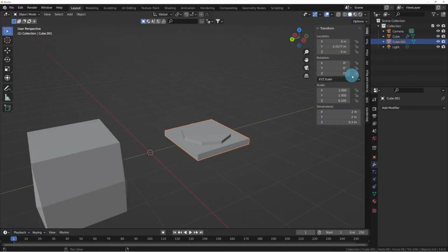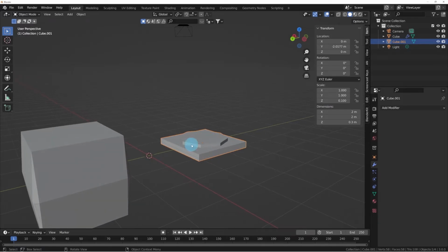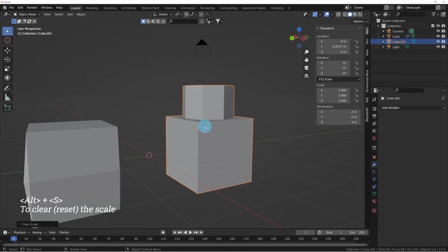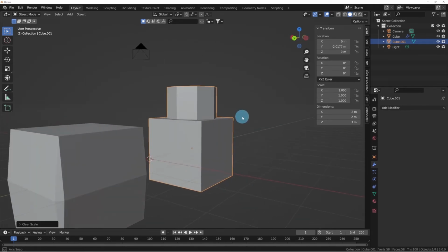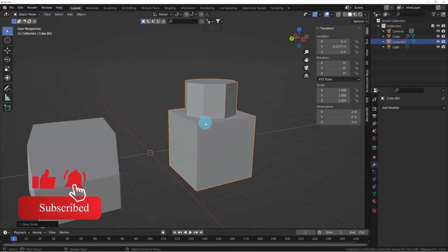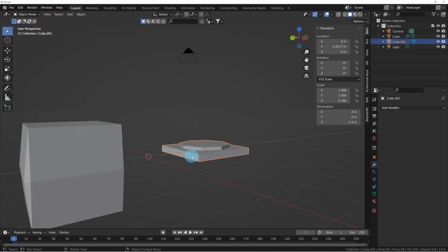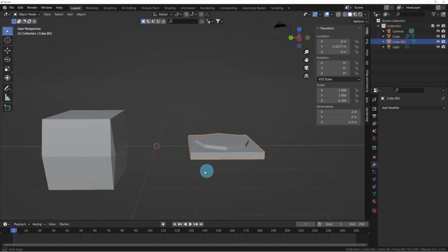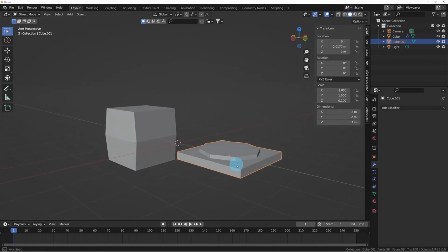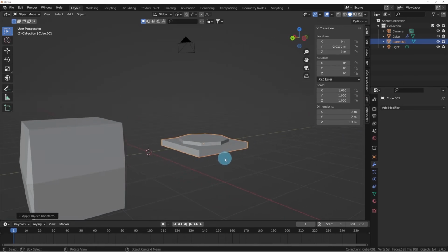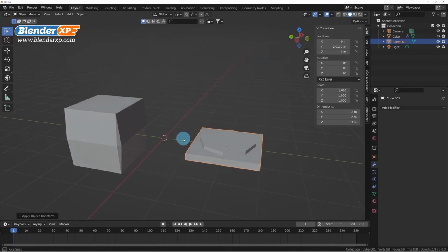This is why it happened: for Blender, this model is actually not what it looks like here. It's actually this. And yes, this is an extrusion of 1 meter. So here, this is the original object. I scaled this on the Z-axis in object mode, which is suitable for animation, not for modeling. You can of course scale in object mode, but just remember to press Ctrl A and apply the scale every time. When you do not want to apply the transform is when you're animating.